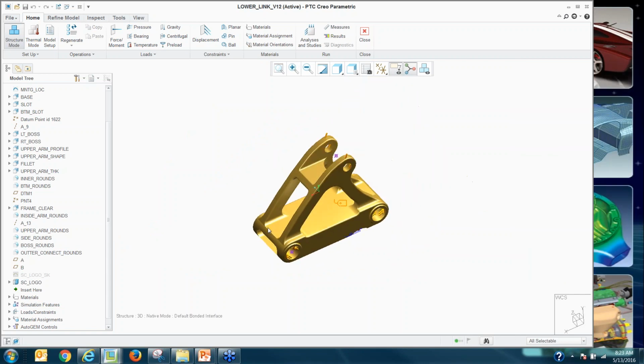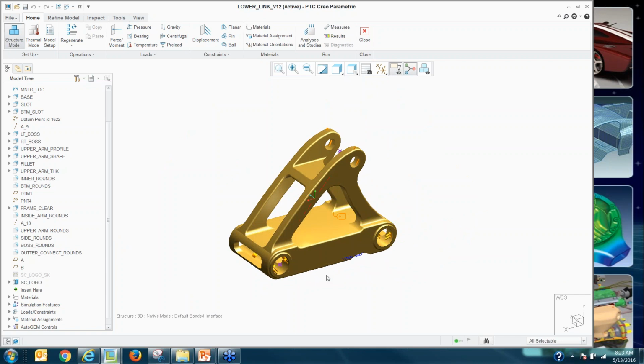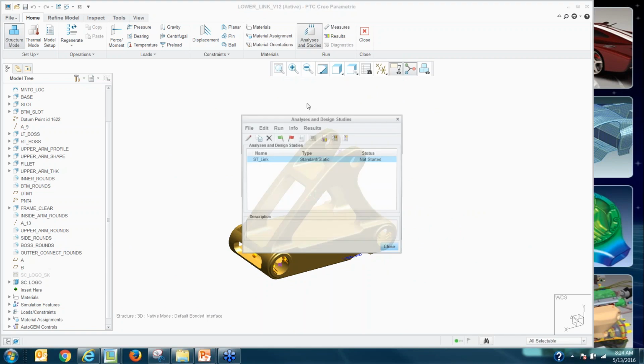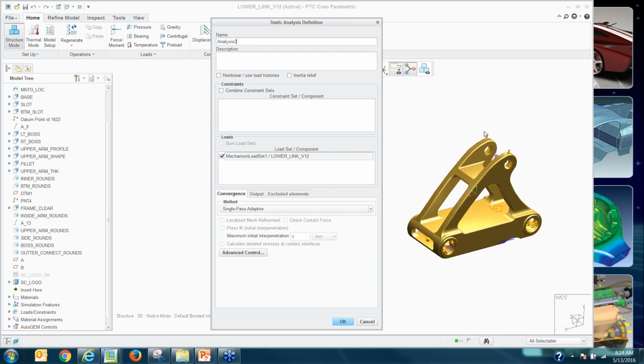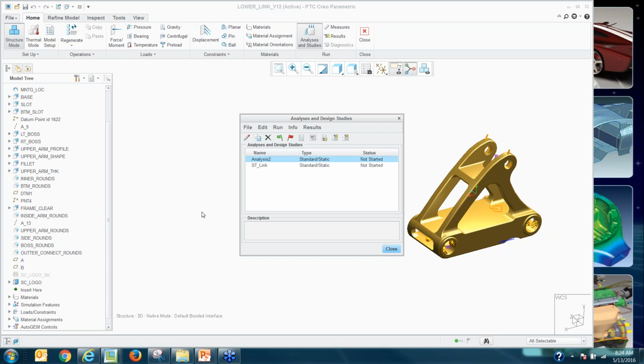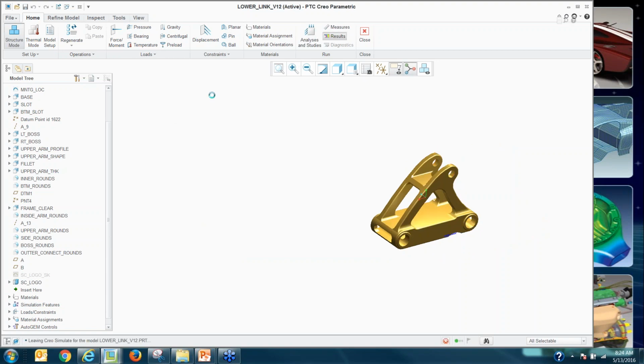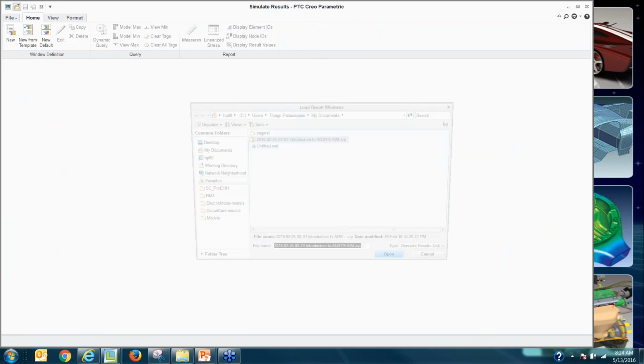on those surfaces. Now, how would we constrain a part like this? It looks like almost the entire part is moving. And is there a way I can use three-point constraint, or I could use inertial relief? When you run a static analysis, yeah, you want to have a constraint, but in this case, for a body that's entirely in motion, you have the option to go inertial relief, which behind the scenes, the software creates opposite body forces, right? So you don't have to apply a constraint, so it prevents rigid body motion. And you could run the analysis, and what you get out of that is like a stress plot, for example.